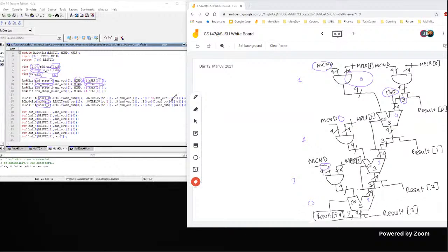Look at the first stage AND output, taking the higher 3 bits and prepending a 1-bit 0. The other input to the adder is the second stage output, all of it, AND out 1. The overflow is connected to the carryout signal, carryout 0, and the adder output 4-bit is here.